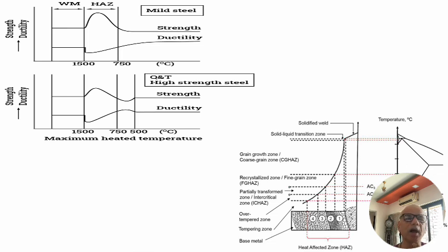variation is surely there. The high strength or hardness and the low ductility happen in mild steel also, and this happens in every alloy, whether it is nickel, copper, titanium, aluminum, or cobalt based alloys. The heat affected zone is unavoidable, and we need to take care of it.